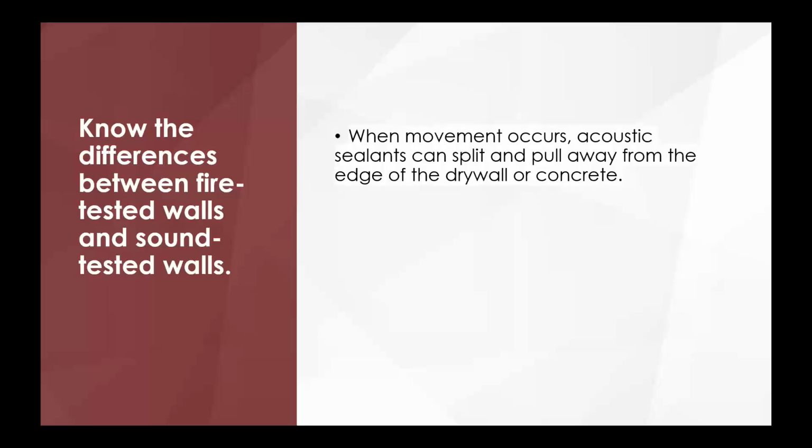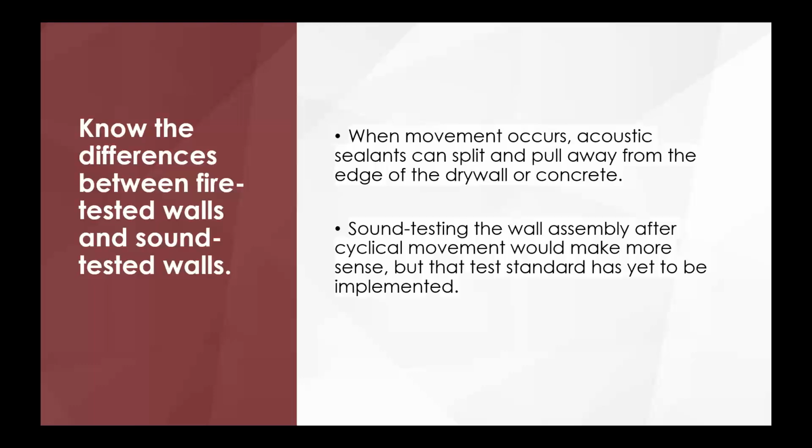When movement occurs, acoustic sealant can split. It can pull away. If it's moving like I just showed in that video, it's definitely going to move and crack. For sound-tested walls, it would make way more sense to do sound testing on a wall after cyclical movement, but that standard has yet to be implemented. If there's anybody on the ASTM codes for sound, I strongly feel that this should happen.